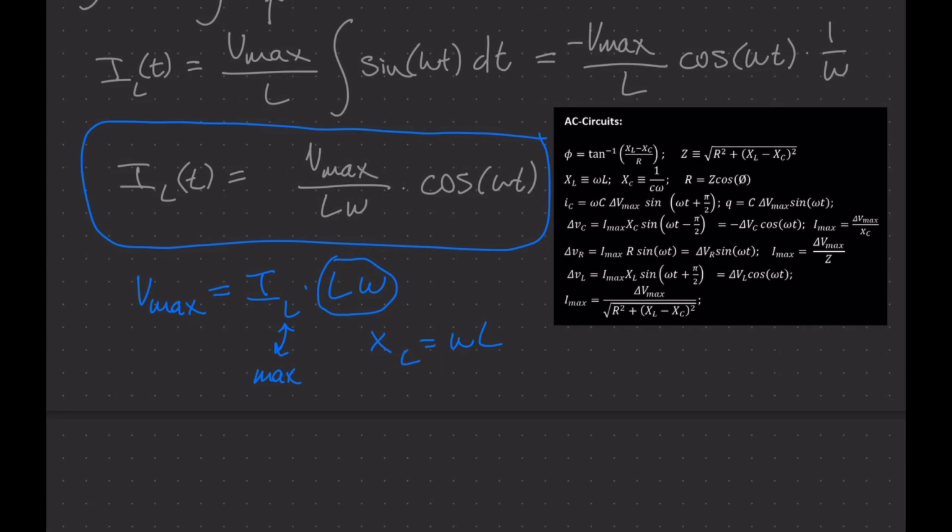So that is why you see these different sine values over here, this one for the inductor, resistor, and capacitor. You can see the resistor doesn't have that phase angle. It follows the same function that the voltage follows. The voltage was, for example, this function. I'm pulling it out from this Q equals CV equation, but imagine just this thing here. This is the voltage as a function of time applied to the resistor.